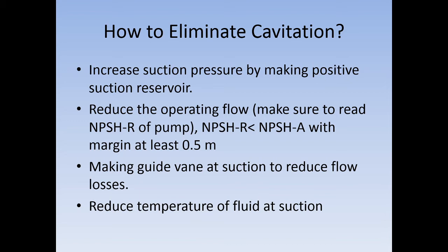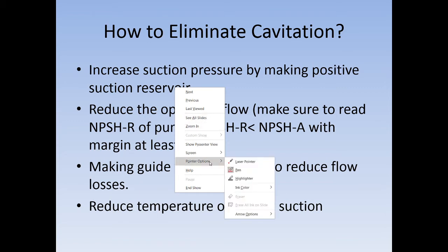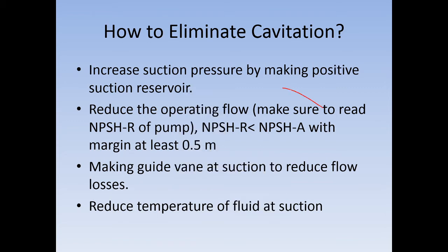And then you can reduce the temperature of the fluid at the suction, but that is not a practical situation on the field. So the second is more practical. So from the beginning we have to size our pump and follow this regulation and our rules of thumb.